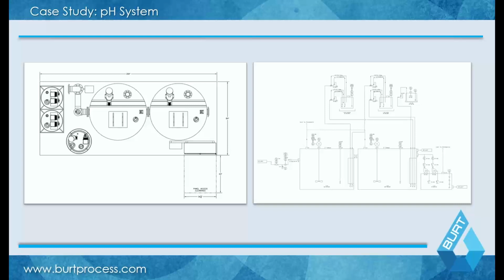And when looking to design a pH neutralization system, understand what kind of footprint and real estate you're going to need to take up in your mechanical space to really account for this. Looking at a P&ID here, you can see you have your lift station feeding in, you have your gravity feed, your two reagent tanks here, acid and caustic, buffer, and this is your two-stage setup with your effluent monitoring. This would be a fairly simplistic style pH neutralization system.